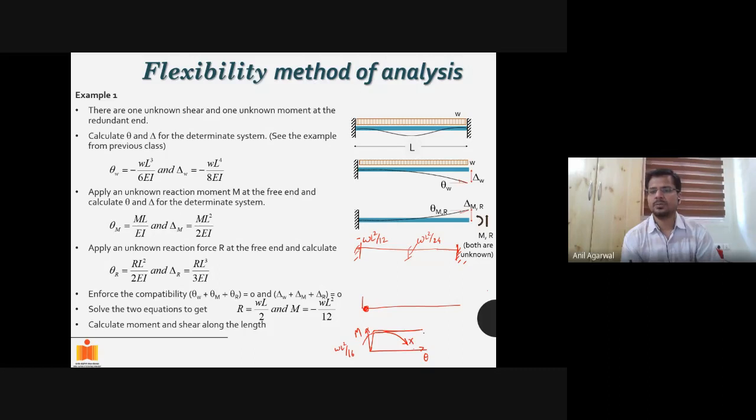So it does not dip, it maintains. Okay, and that can be assured by making the cross section more compact. If we make sure that the cross section is more compact, it does not undergo local buckling even after a very large amount of yielding.